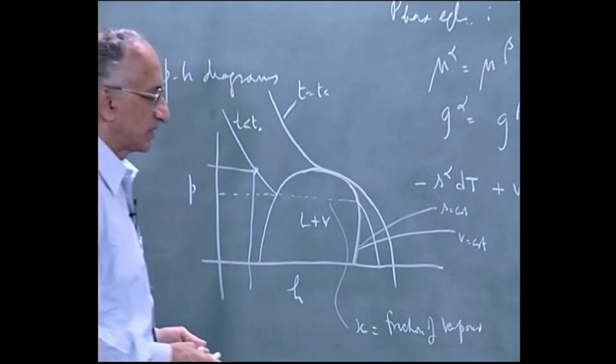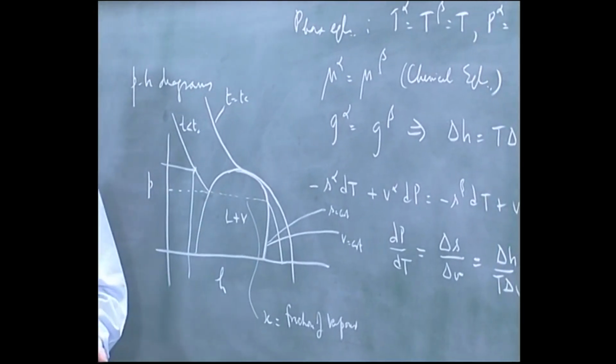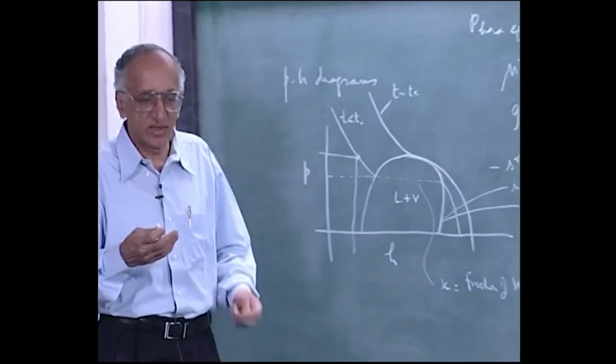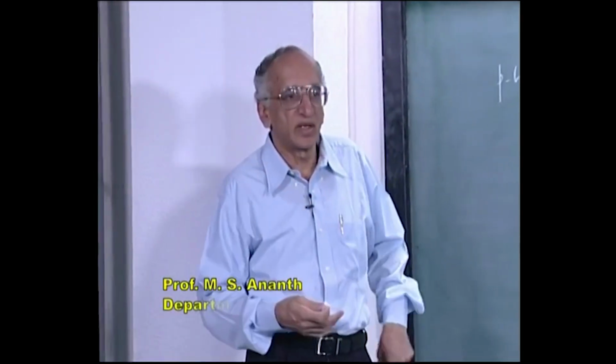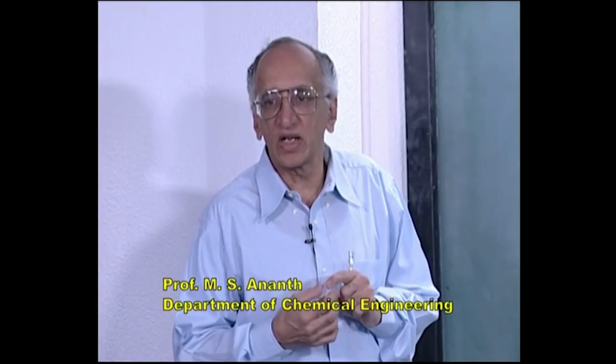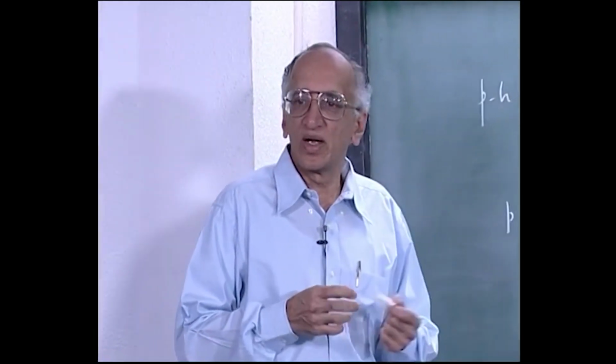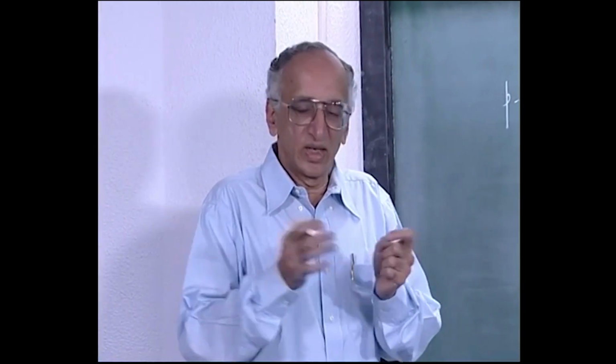Now if you want to calculate work, for example, you want to know what is the maximum work. Typically, for example, you compress a fluid, you compress it, as I said, adiabatically, simply because compression is usually done by, it can be done by a rotary device or a reciprocating device, and the compression time is very small. It is so small that the amount of heat transferred to the fluid is negligible. If you take a rotary device, for example, typically it rotates at 1000 rpm or 1200 rpm for convenience. That means per second you have 20 rotations. So in 20 times a second it gets compressed. So 1/20th of a second, how much heat can be transferred to the fluid. So effectively it is adiabatic.